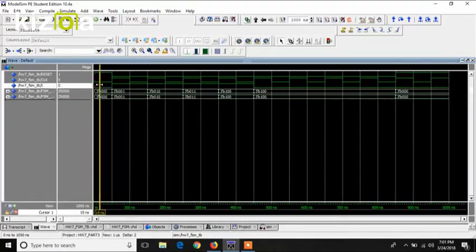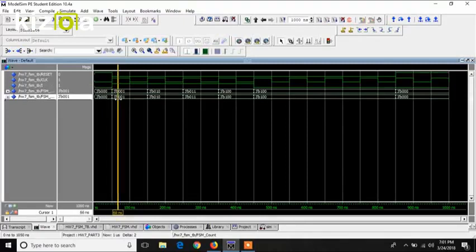So it starts off with reset being 1, and so therefore everything else is reset, cleared. And at the first rising edge, clock is 1, the input is 1, then it goes to the next state, which is 1, 0, 0, 1. And then at the next clock edge, it goes to the next state, which is 2.